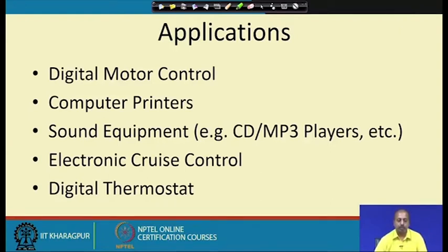So, there also we have applications of this DAC. Sound equipment like audio players, basically. The volume or the pitch, the signal that is controlled by the processor, is given to the player. Before that, this digital value has to be converted into analog. Most of the songs and media data that we have are digital in nature, so when you put it onto a player, we have to convert it into analog values.